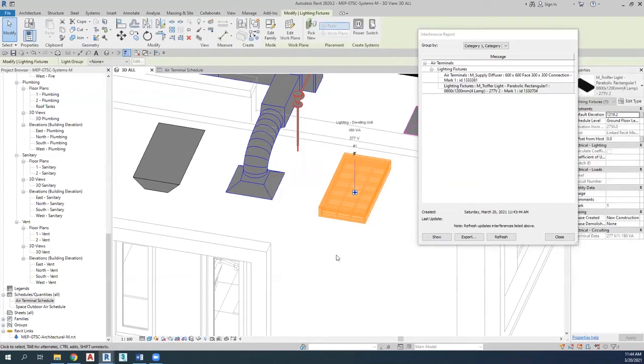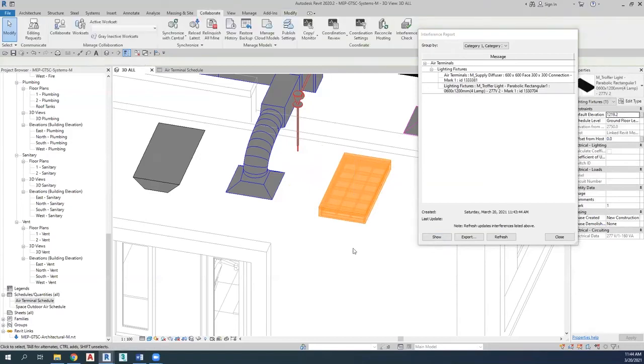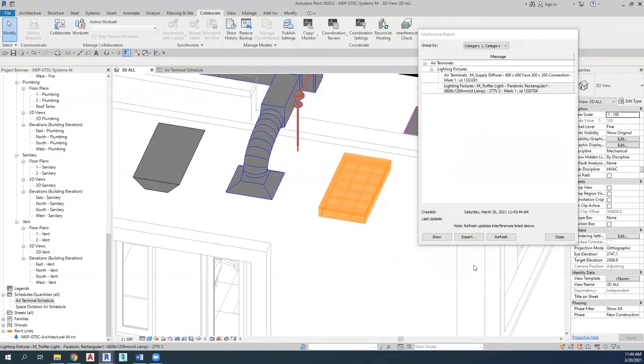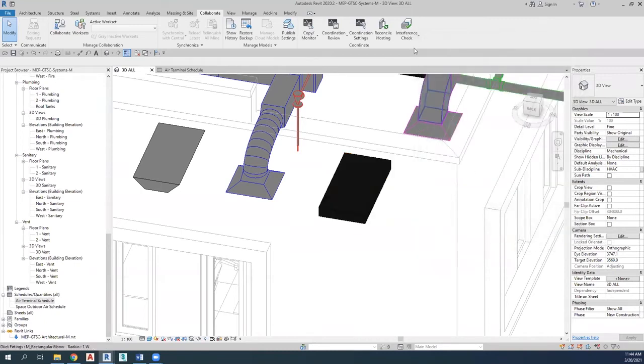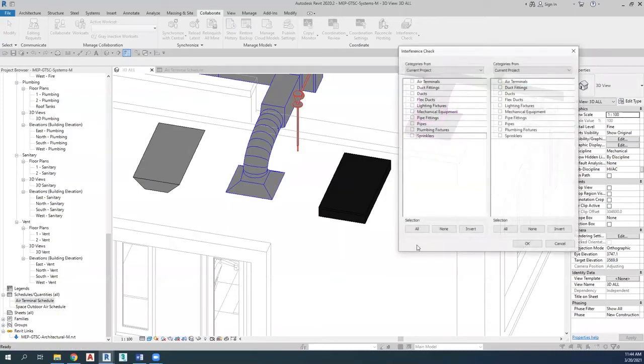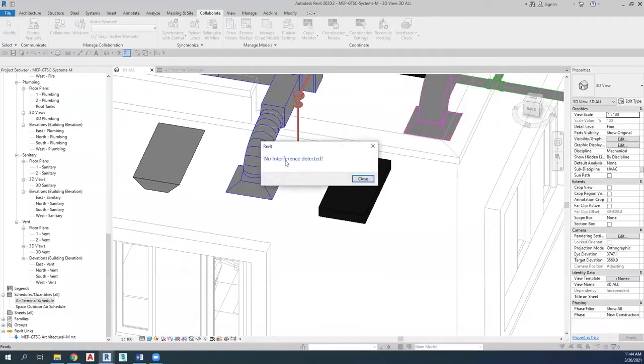After fixing the clashed items, you are not obliged to make a whole new report. You can simply click on Refresh, and Revit will either showcase the newly modified report, or a blank page for no detection of interference. When trying to experiment with reviewing the report, a No Interference Detected pop-up notification will show, to inform you of the absent clashes in your project.